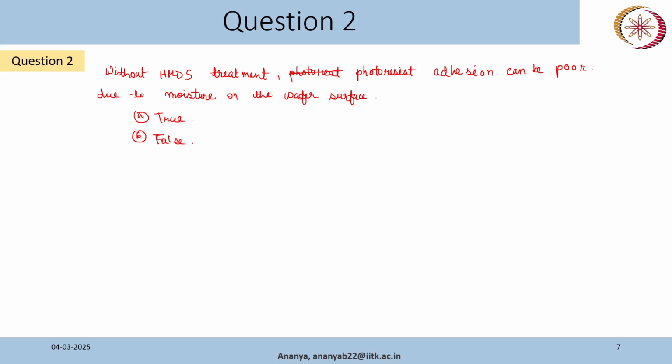And one more thing I want to say, that these are from my personal experience. What we do in our labs when we do lithography, and when we operate any machine, we try to control the humidity level as well. In the class we discussed different clean room protocols, and we are already aware of different kinds of filters so that there is no contamination. One more important thing is that you maintain the proper temperature and humidity while doing some processes, because that will also affect your end result significantly.